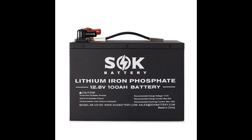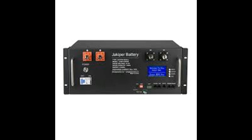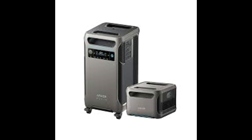Now, something that I read and hear frequently, somebody will say, I have a 200 amp hour battery pack, and they'll be asking how long can I run a 120 watt bulb, or appliance of some sort? And the answer is, you don't know. There's no way for you to know how much power is in their 200 amp hour battery pack unless they give you the rest of the picture.